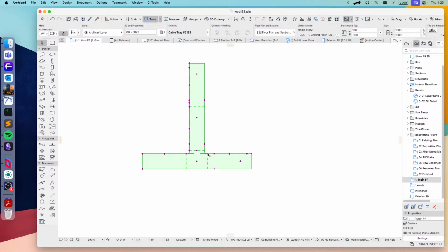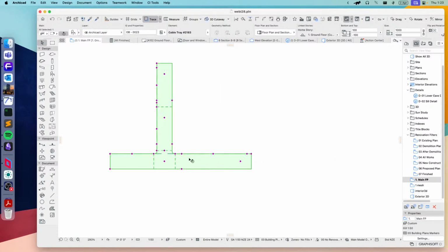T here. We'll start with this first hotspot here. So if I select this hotspot, you can see as I move it that the length of the edge, so that is the edge here, is extending out as I move that. So we can extend the edges and then grab the second hotspot and move that up, or well, in this case, sorry, downwards on screen, and it adds a reducer here.